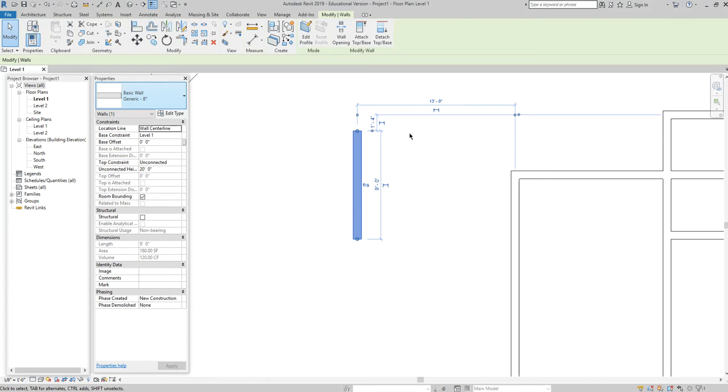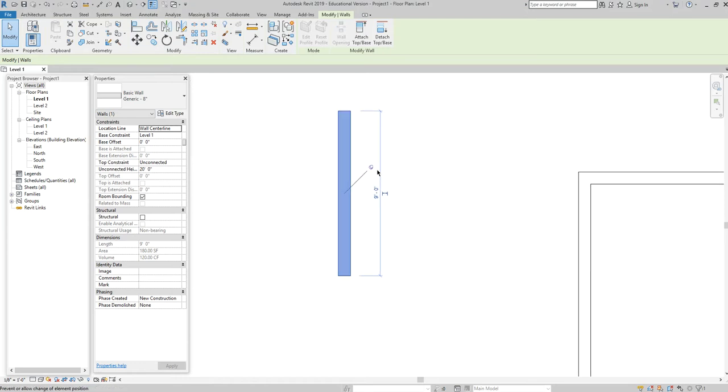So I click on the object I want to pin down, and when I do that, the little thumbtack pops up here. Click, and it's pinned, and I see a little thumbtack right there, right? Sometimes I feel like Revit uses terminology just to be different than AutoCAD, and you wonder, why don't you just call it locking it down, which is what we do in AutoCAD? You're owned by the same company, the same people use your software. All of a sudden we pin things instead of locking them, right? I guess it doesn't matter.